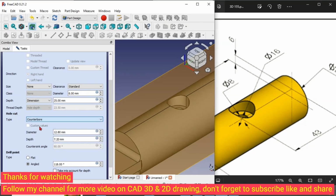For counterbore, we have a few selections here, countersink and also counterdrill. For this drawing, you just take a counterbore. For the counterbore, the outside diameter is 16. We change this to 16. Then the depth is 6.